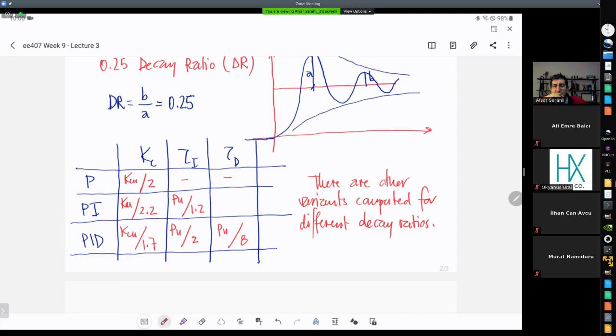So you find from which side of the gain you can approach instability, and you find the boundary of instability, and then you back off a certain amount in order to obtain a reasonably underdamped controller response. Okay, this method is in practice very useful.